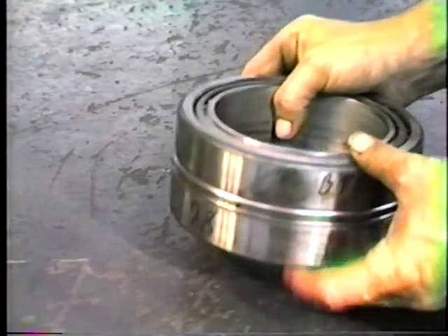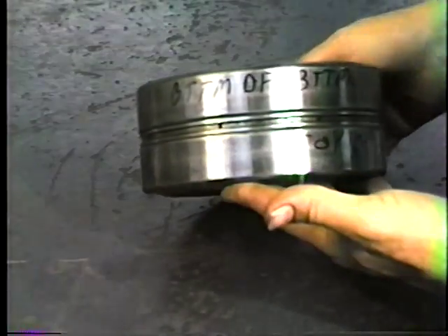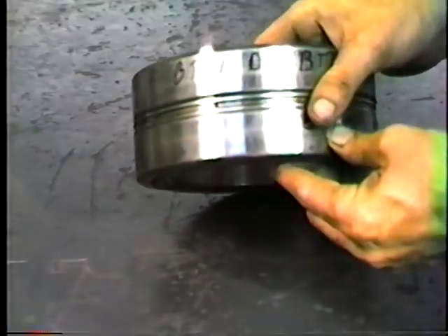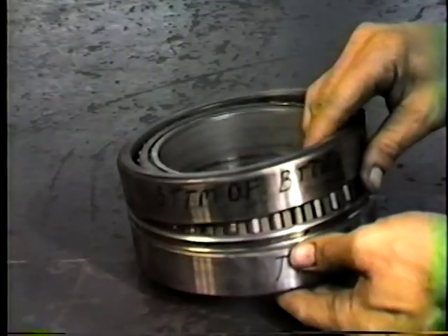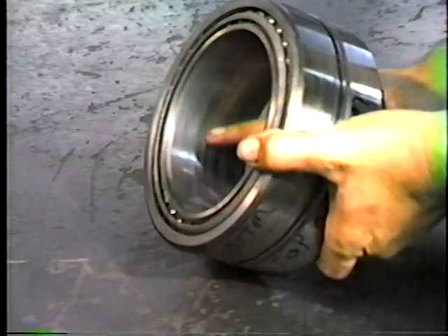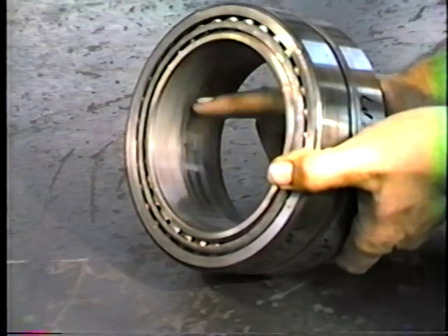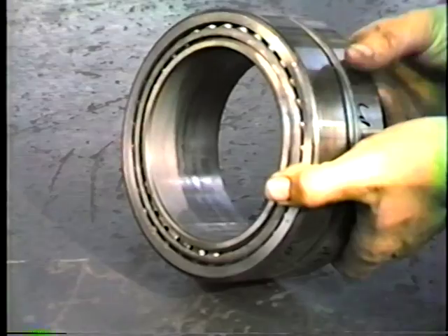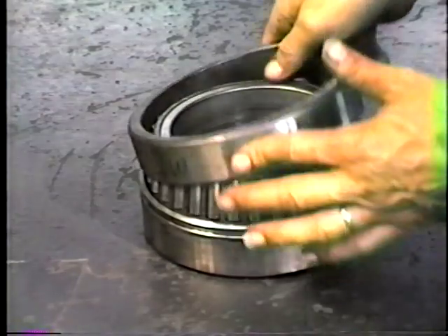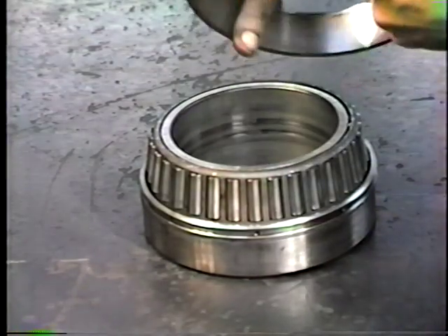That was the bottom and top. You can probably see that one better at the bottom. Bottom of the bottom bearing. And then that has been the top, with Mobil Temp 78, right? Right. Those are both out of the same journal. It shows the square here, the grooves where it's worn. That's the bottom bearing, and it's obviously turned on the shaft. Apparently the friction on the bearing itself is greater than the friction on the shaft.